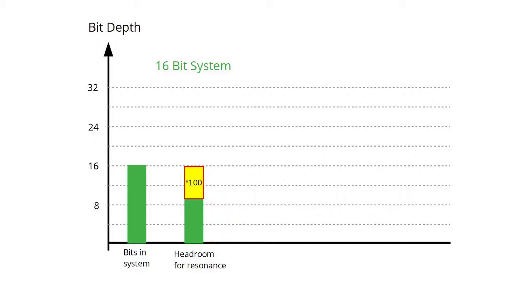In practice, in 16-bit systems, I'd probably use 12 bits for the oscillator, since we're not using a sine wave oscillator, so the output of the filter will never be quite 10 times, and if it does clip, it just clips, and we'd have to live with that.